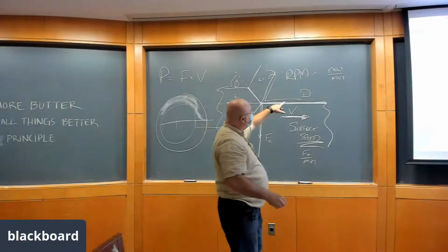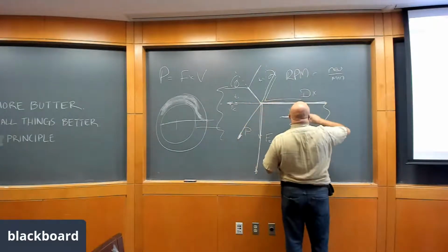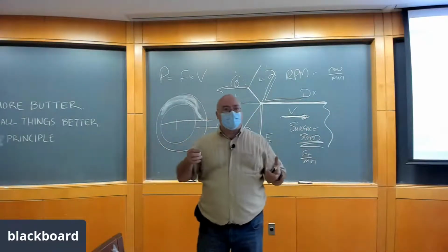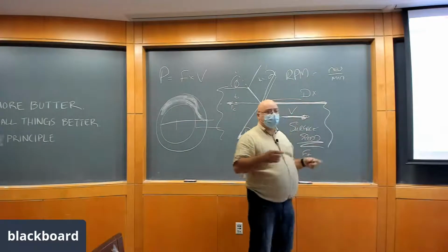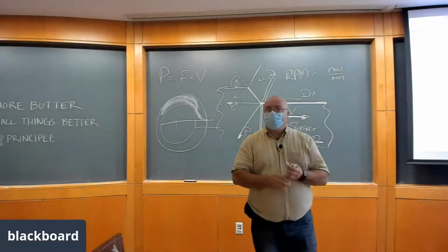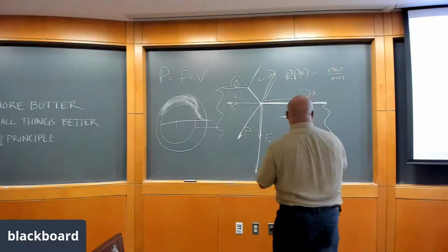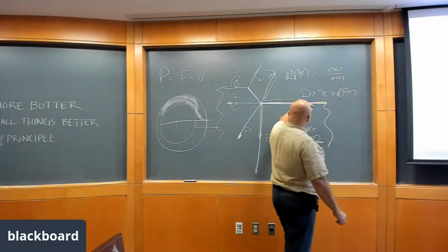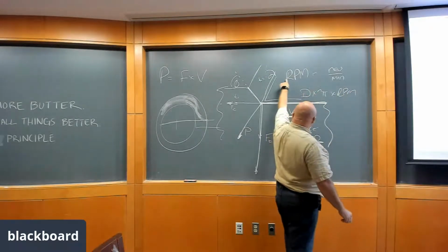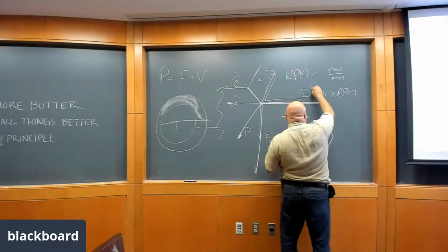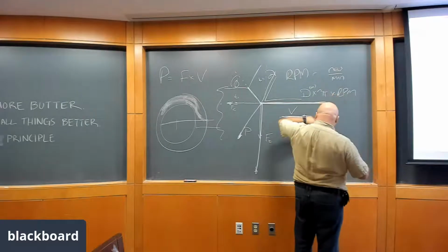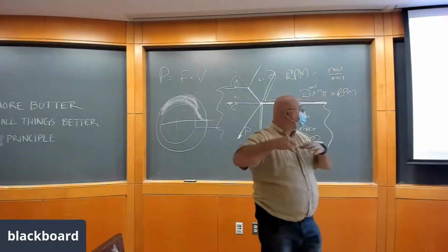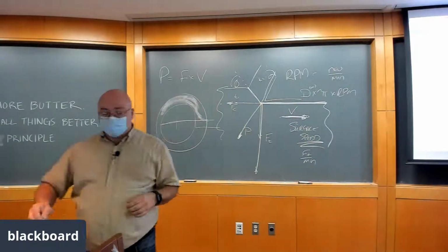And so diameter times... Modeling of manufacturing processes, modeling of any process like this, is often creating an equation. So diameter times pi times RPM. Our diameter is typically in inches, and our RPM, or what we're looking for, surface speed, is typically in feet. So we have to add a factor of 12 in somewhere to convert from inches to feet. Okay, so our velocity,